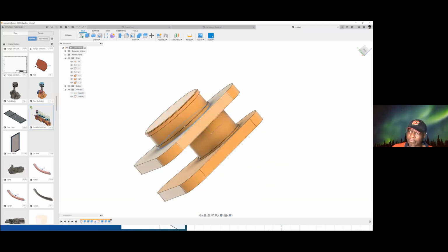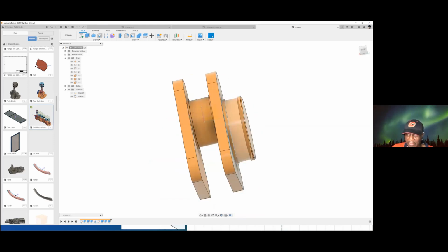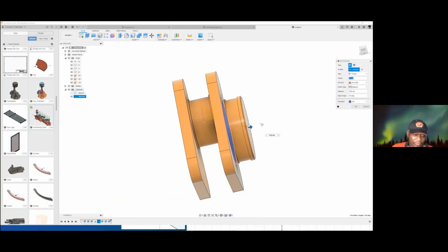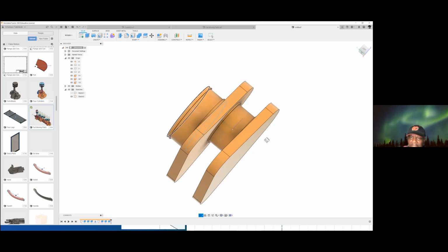So if you look again, you will see that this is looking like you want it to look. So this one, I started too early, so let me move it out. So let me edit that feature. Edit the feature. We should do an offset of 25. Okay, so it's better now. So set it at 25, and then you can see this.